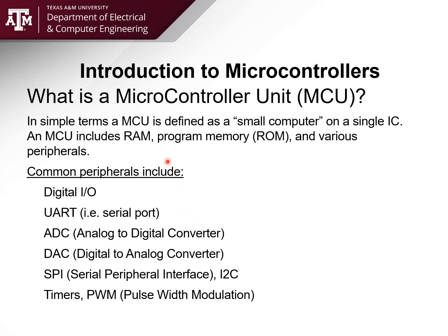And I was just using one the other day for a simple project. And actually, that single chip, small 8-pin, literally the same package that an operational amplifier was in, the same physical package, had digital I/O, it had serial ports, and it had both an analog and a digital converter. It supported these communication protocols named SPI, serial peripheral interface, and I2C. These are just communications technologies for going from chip to chip, so you can actually interface more analog digital converters and the like.